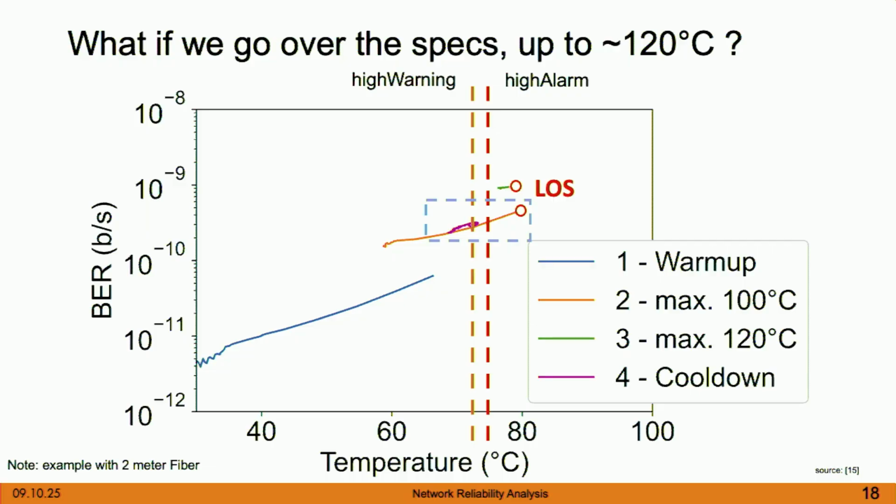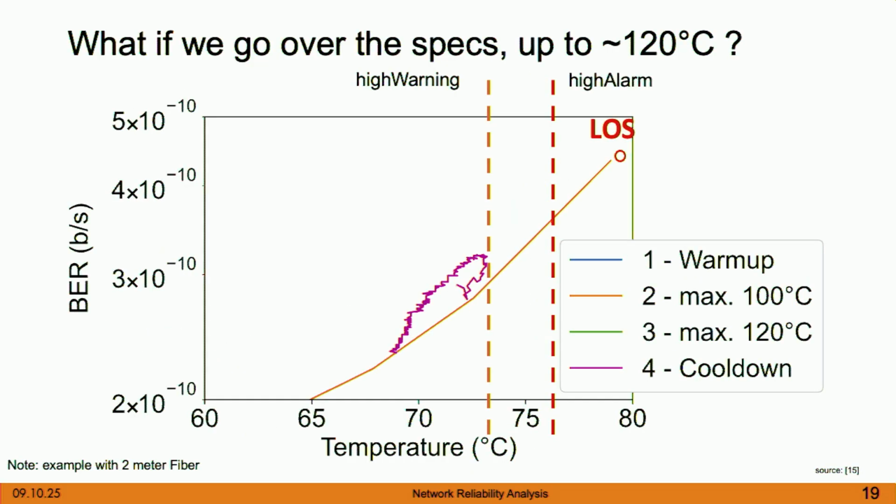That is the temperature we usually take. We try to be very secure in this aspect. Then I removed the secure and rebooted it, and then it passed. And as you can see, up to 100 degrees at 80, it loses the signal. So it is lost. I turned everything off. I tried it again with 120 degrees after briefly cooling down. It worked, but around 80 degrees it gave up, loss of signal.